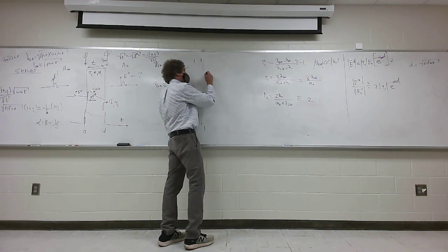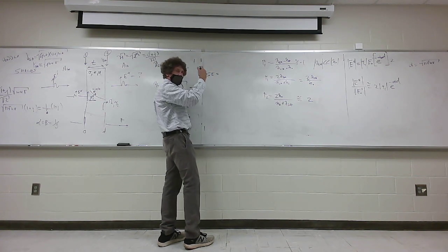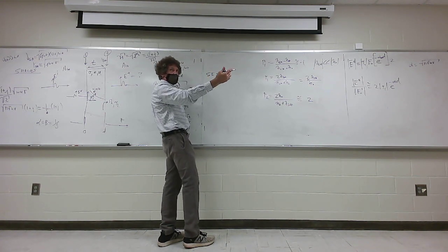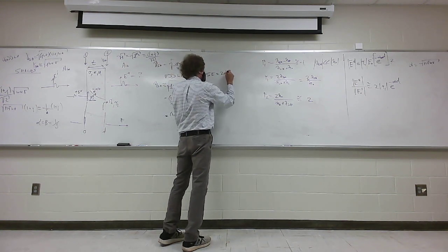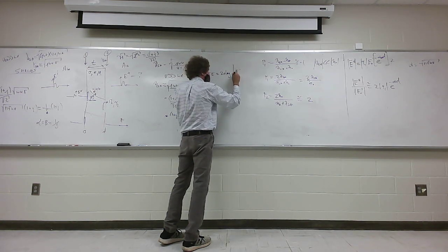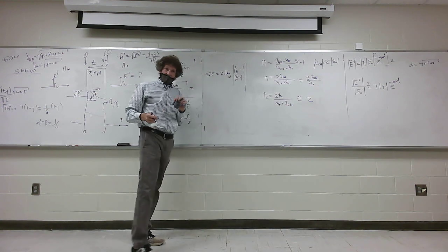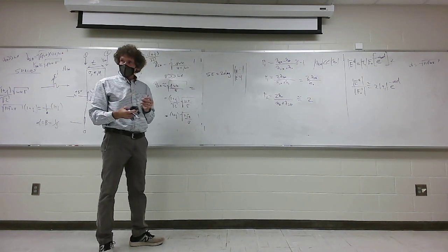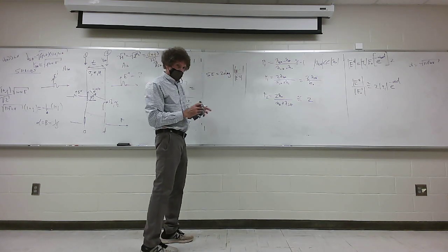So when you talk about shielding effectiveness, it has a positive number even though it means attenuation. It's 20 times the log of the magnitude of the incident field over the transmitted field's magnitude. Y'all follow me on that? It's just the ratio, but it's an inverse ratio. You with me? Now if they put a negative sign in front of it, then they reverse those.